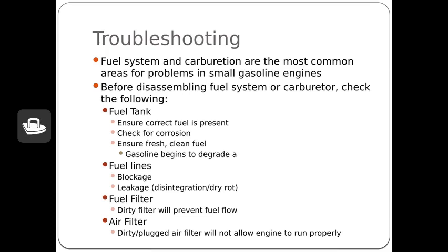And that usually ends up being something like dirt or debris in the carburetor, or commonly has to do with ethanol fuel. Now, I want to take a moment and talk about ethanol fuel. Ethanol is a fine source of energy in engines that are rated for ethanol. Most small gasoline engines are not ethanol compatible. Now, I know some of you may be thinking, well, I use ethanol mixed gas in my lawnmower all the time, and to be quite honest, so do I.